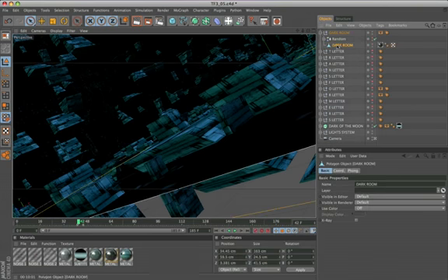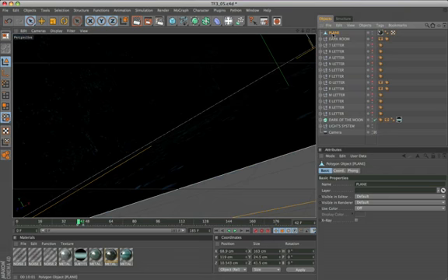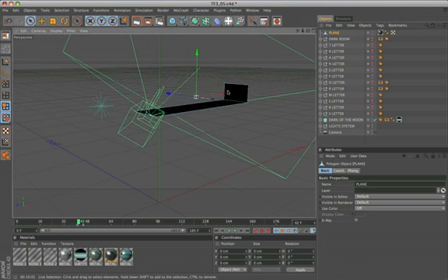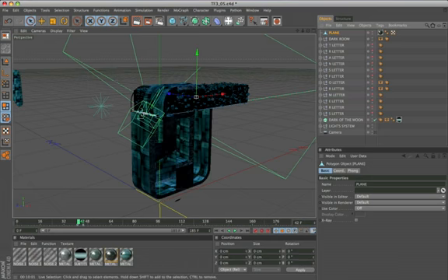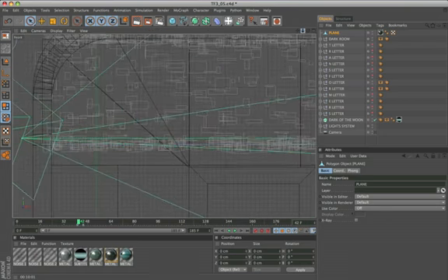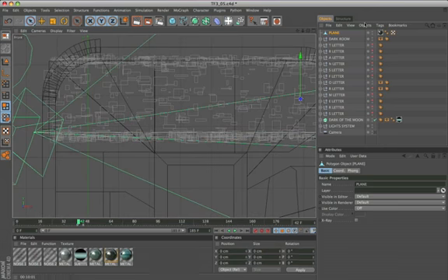OK, duplicate the darkroom layer and rename it plane. Delete all faces except the bottom. And with the help of the front view, move it along the x-axis to align with the edge of the letter O.